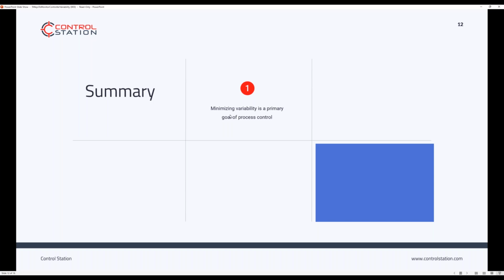You focus on the KPIs and the metrics that are going to get you better statistical process control, because those are the final numbers, right? That's telling you your production, your energy consumption, your percent of quality widgets, whatever it is. Your statistical process control is that final out-the-door number. Your individual PID control performance is really about understanding all the individual control loops or systems in your plant that impact the variability of your widgets, of your process, right?